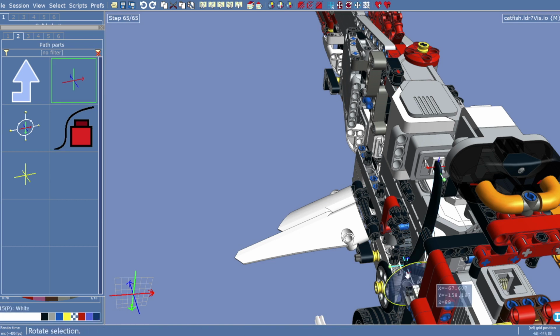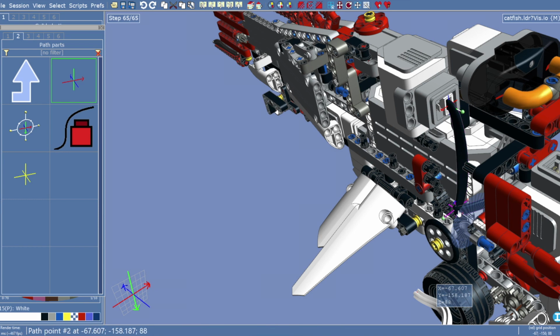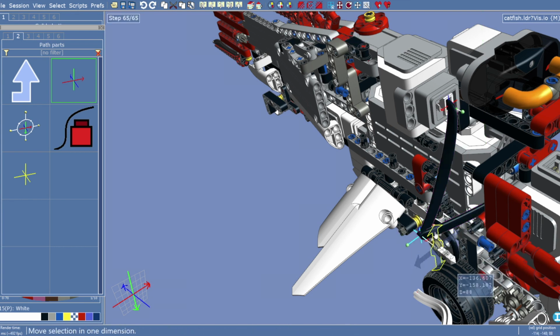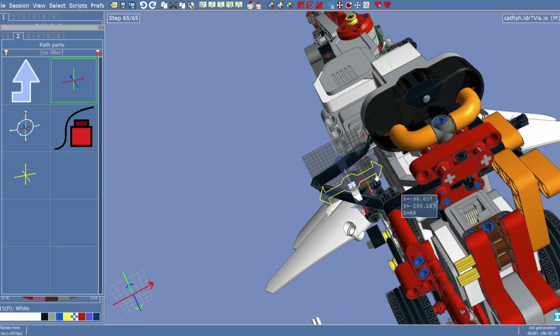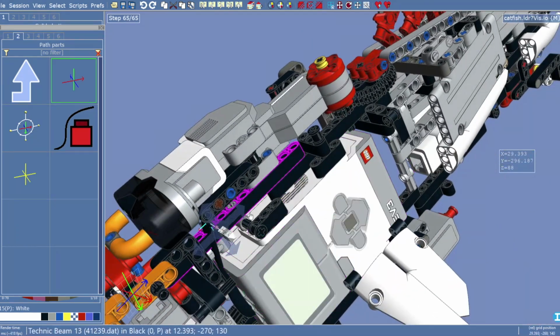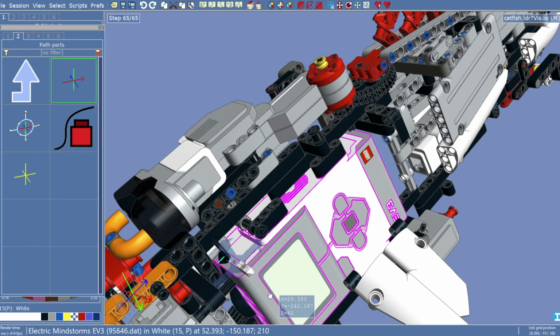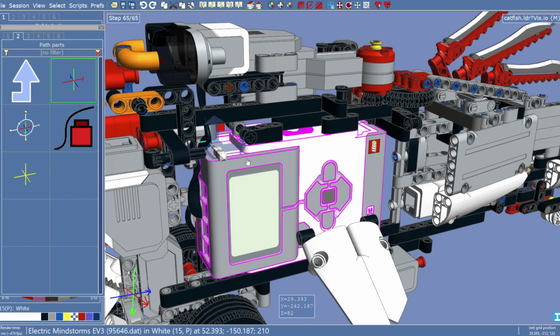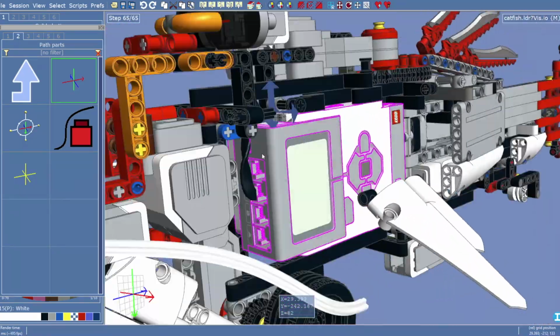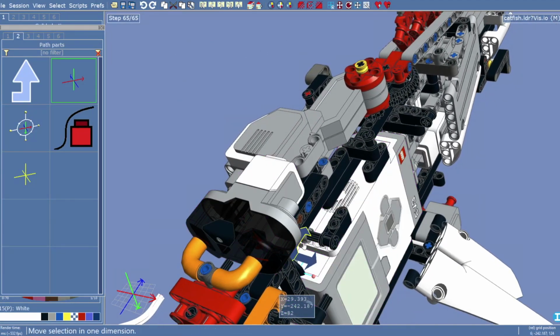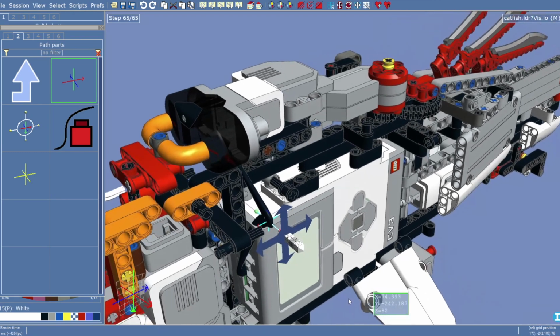and the point is just like a part. You can move it around. So moving around stuff in LDCAD works with this weird widget here. It's got 3 modes. One mode moves the origin, and this mode translates it, and this mode rotates it. So let's first go to translation mode. So I get these arrows where I can move the Bezier point around. Yeah, I think this is a nice location for a Bezier point, right here on top. And you can see as you rotate your view, the directions of these arrows will rotate with your view.